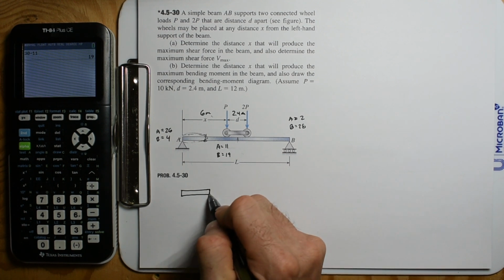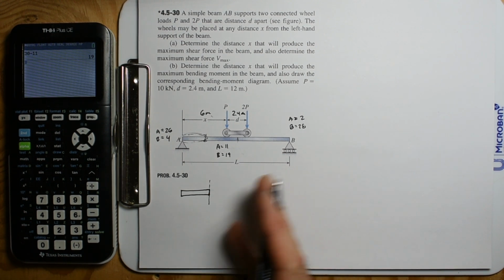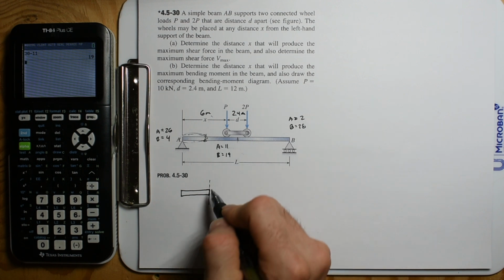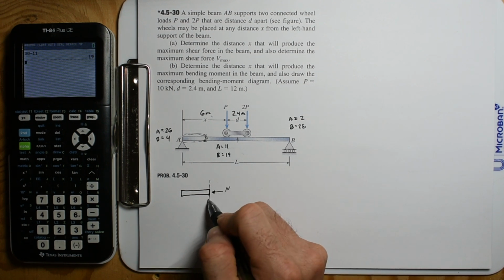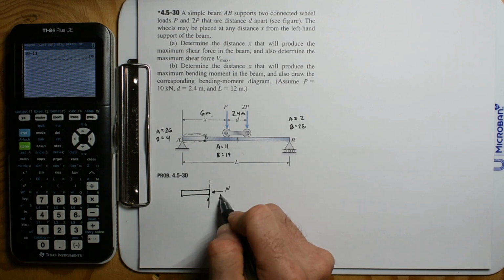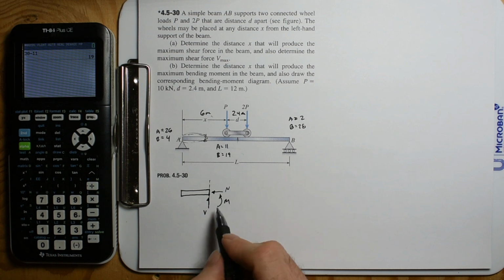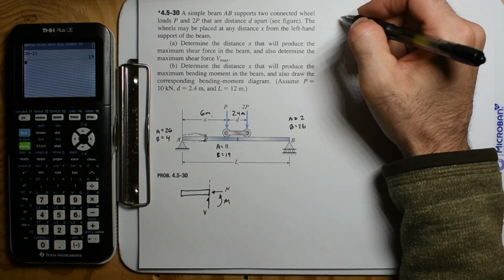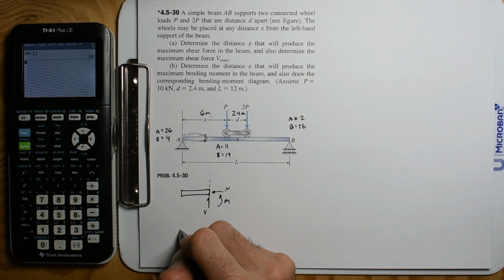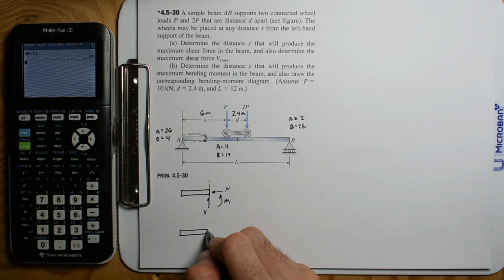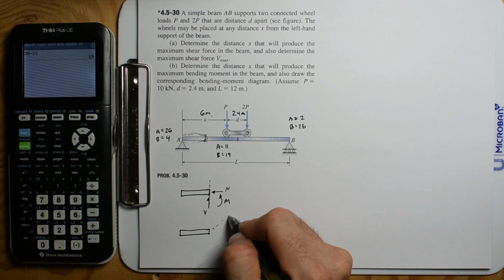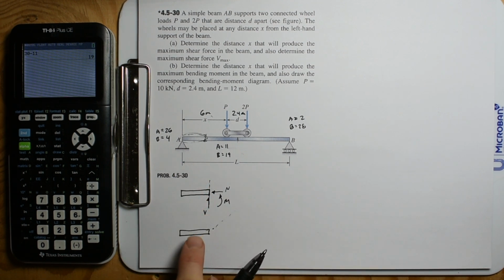And we chopped it. Right here where we chopped it, we really don't know anything going on at that point, but we do know there can be a normal force, there can be a shear force, and then there can be a moment. Those are the things that we can always add in. I shouldn't have drawn it like that at all. Let's just draw it without that, because it's interesting just to know your cut is going to be right there. But then add the things that you do know.